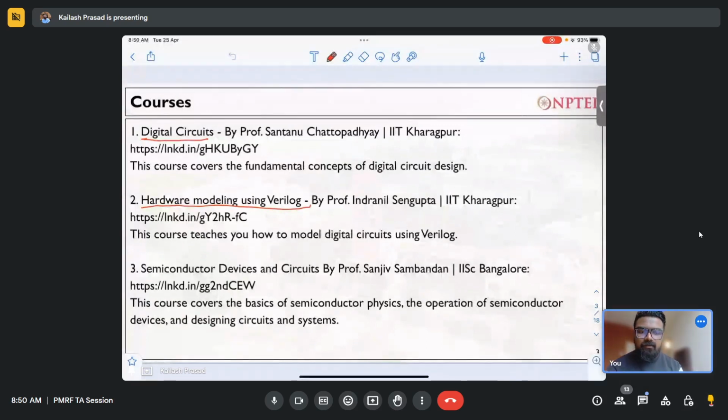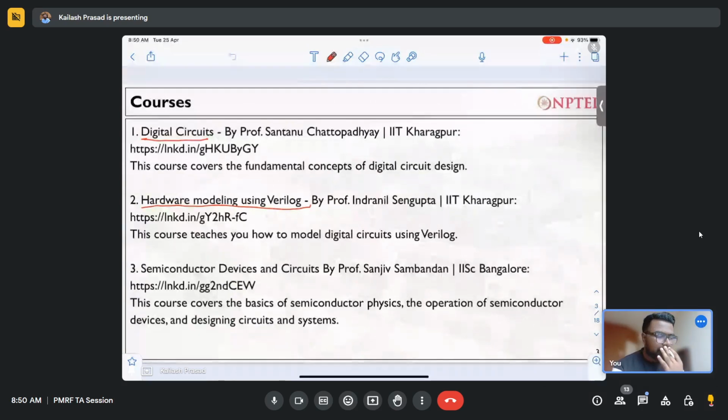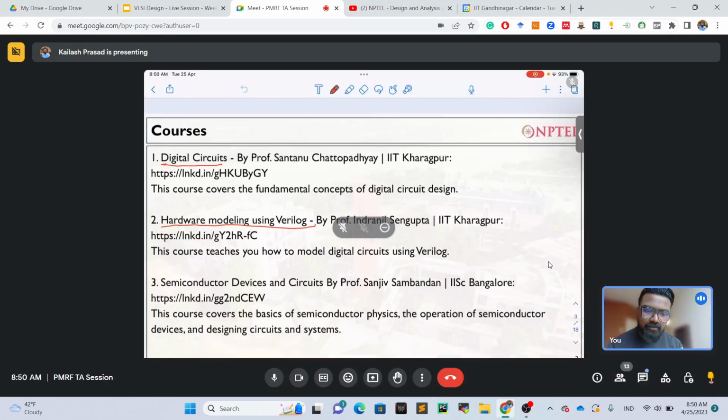Yeah, so what I was discussing is the new kind of devices, the complementary field effect transistors. This complementary field effect transistor will be in the latest advanced technology nodes, where the NMOS is actually built over the PMOS, such that you reduce the area footprint. These kinds of new innovations are going on in the device community, and this is very important to take care of. That's the reason this course becomes extremely important in that regard.